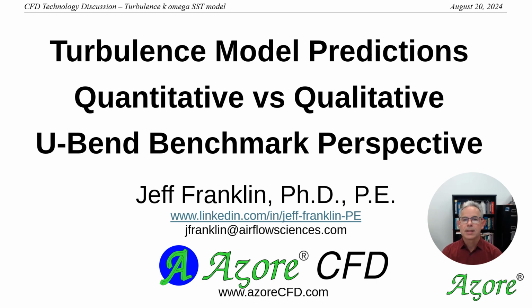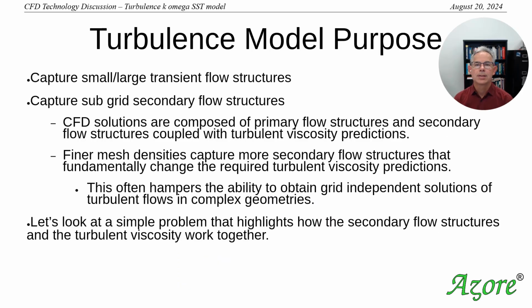So let's get started. The first thing I'd like to talk about is what is the purpose of a turbulence model. The first thing you want to understand is that a turbulence model wants to try to capture these transient eddy flow structures that are always around. A small structure is a small eddy that maybe grows and shrinks, but it's at a very small length scale and it grows and shrinks very rapidly.